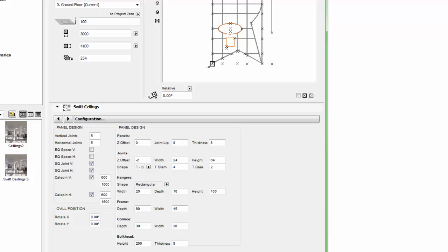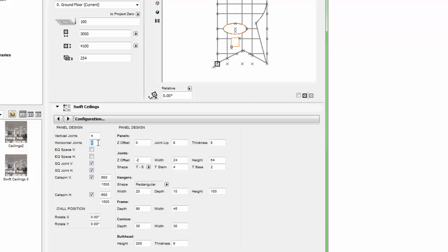That's basically just going to be the placement of the joints interfering with certain things, so I'll show you how that works. It seems this joint here has fallen completely out, so we can turn that one off. So that's number 5 of the vertical, so we'll just go down to 4. And this one here is going to be getting cut in a strange way and giving some bad results, so that's probably why that's not working.